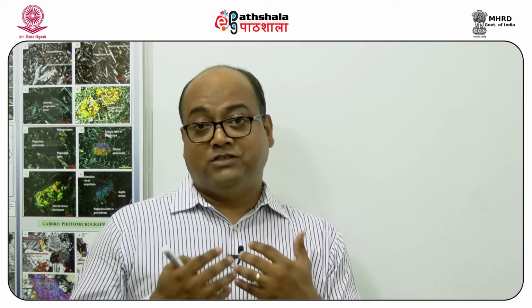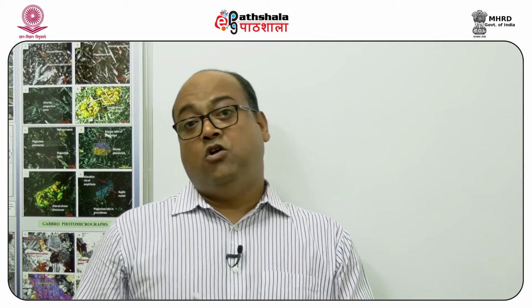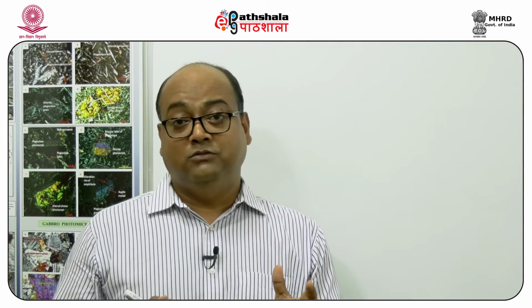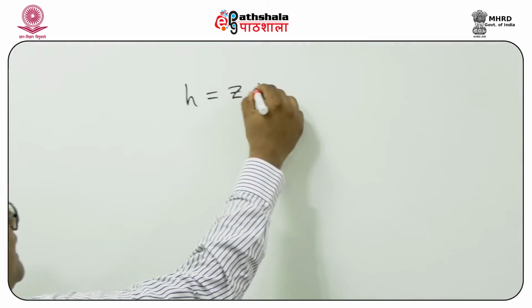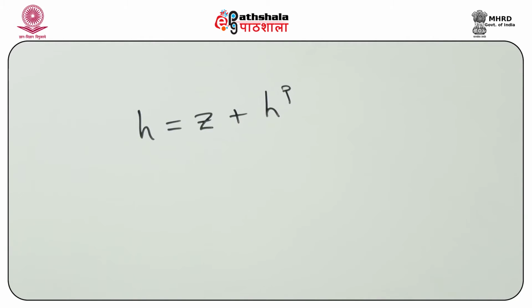And as I was talking about, the movement of groundwater is not dependent either just on the elevation head or just on the pressure head. It depends upon the sum total of the two. So if I rewrite the equation, hydraulic head is equal to elevation head plus the pressure head. Now, just to better illustrate, I'm going to draw two different conditions.